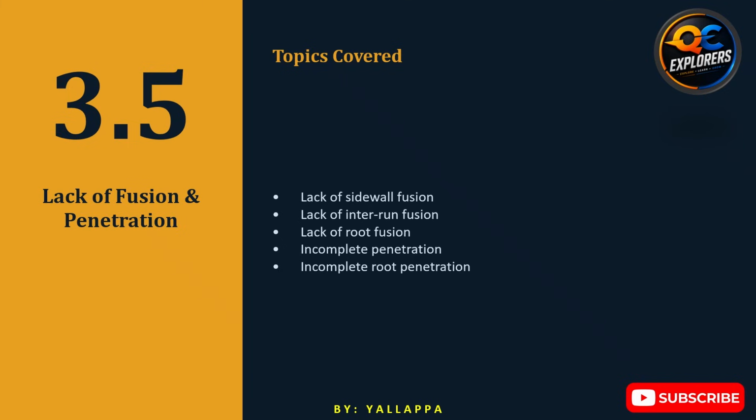They may therefore be more structurally significant than small rounded pores. Prevention begins with correct joint preparation, correct welding parameters and appropriate welder technique. The inspector should therefore not wait until the final weld to think about fusion. Root gap, root face, bevel condition, cleanliness, welding current, voltage, travel speed and electrode manipulation can all influence the final result. We will now look specifically at the types of lack of fusion.